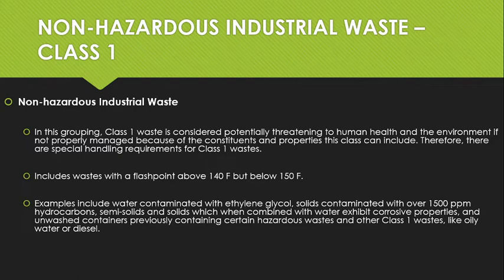So, for example, that's why we can't send, without testing, diesel and soil to Waste Management Austin, is because they can't accept anything that's class 1, only class 2. So just more considerations, and why I need SDS sheets, why we need analytical testing is to figure out, okay, where can we send this? Who can accept this class 1 waste?